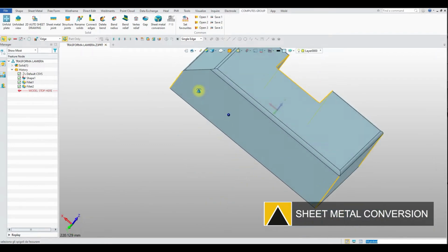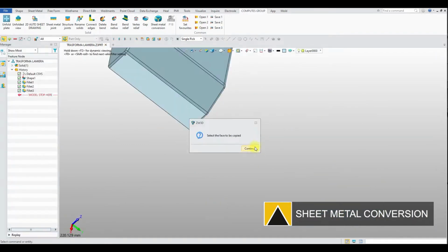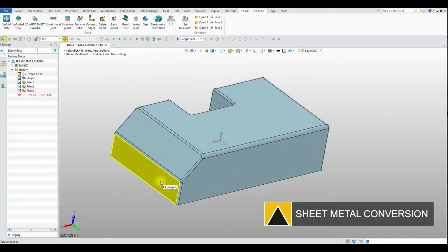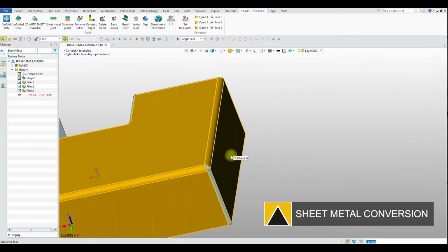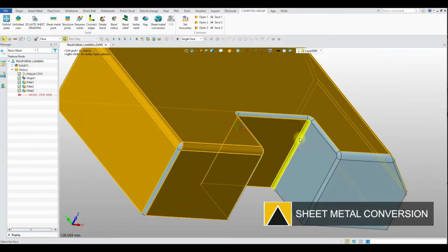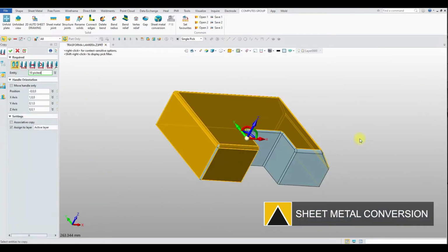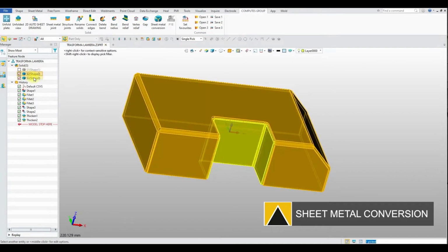How to use: set the bend radius and the thickness. Select the edges where you need the external radius, the internal radius, and the slits. Select the faces of the solids that you want to keep in order to split the shape. The created solids will not be linked to the original solid.